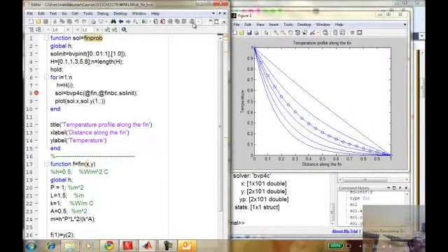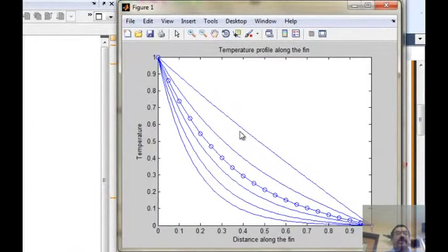Okay, so you can see clearly as you increase the heat transfer mechanism by increasing the fan speed, you are bringing the temperature down very rapidly. So the tip of the fin is going to be much cooler. Then you have a lower value of heat transfer coefficient. The last one is for H of 8. The first one is for H of 0.1. So this gives you the tool as a process engineer to analyze problems for varying operating conditions.